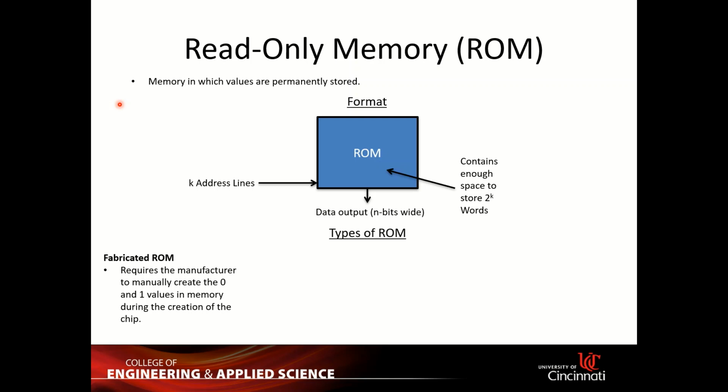The programmer can give certain 1 and 0 inputs into the PROM, and when you put a high voltage and high current through a fuse, the fuse blows. Boom. Now those fuses can be your permanent switches.